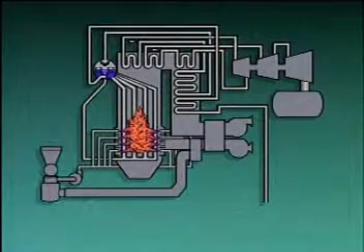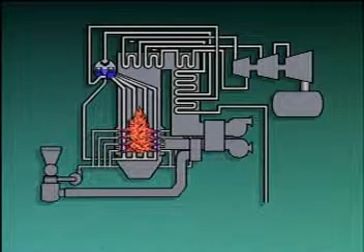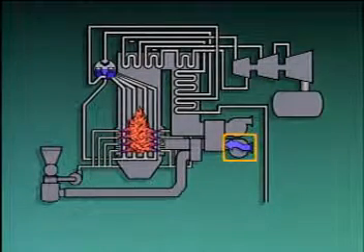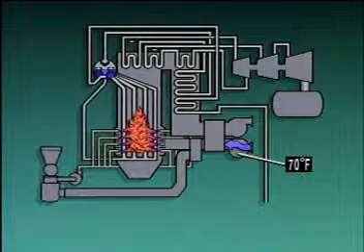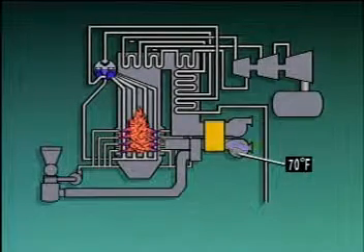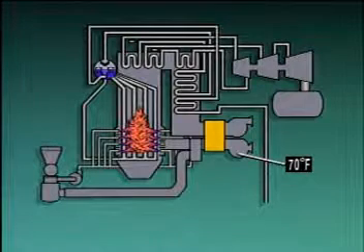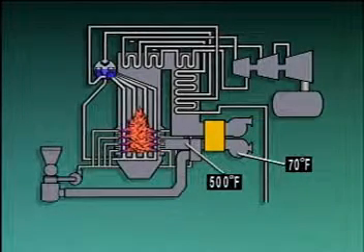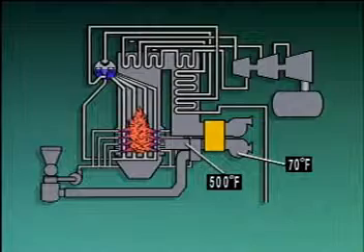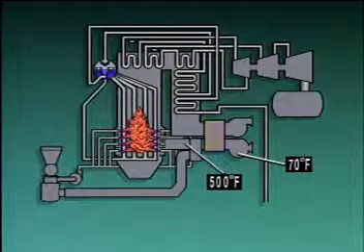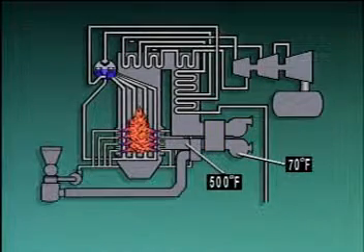Let's take a more detailed look at a typical coal-fired boiler to see how this works. Airflow starts at a forced draft fan that takes in air at atmospheric temperatures and pushes it to the boiler. In the boiler, the air passes through an air preheater where its temperature is raised to about 500 degrees Fahrenheit. There are two common types of air preheaters, rotary preheaters and tubular preheaters.